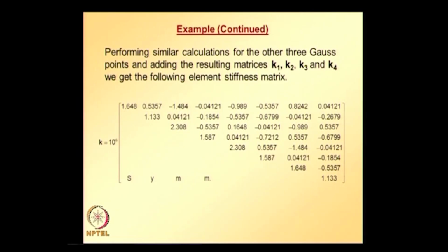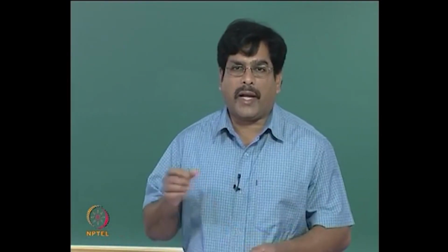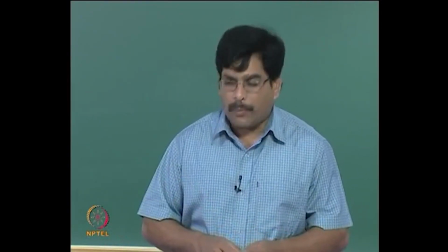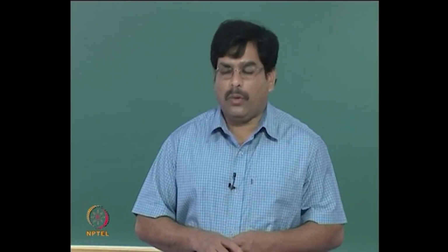So we obtain the element stiffness matrix, and there is not much involved as far as assembly of the equivalent load vector is concerned, because all the loads applied are concentrated loads, so we just need to plug in the corresponding value at the appropriate location in the load vector.